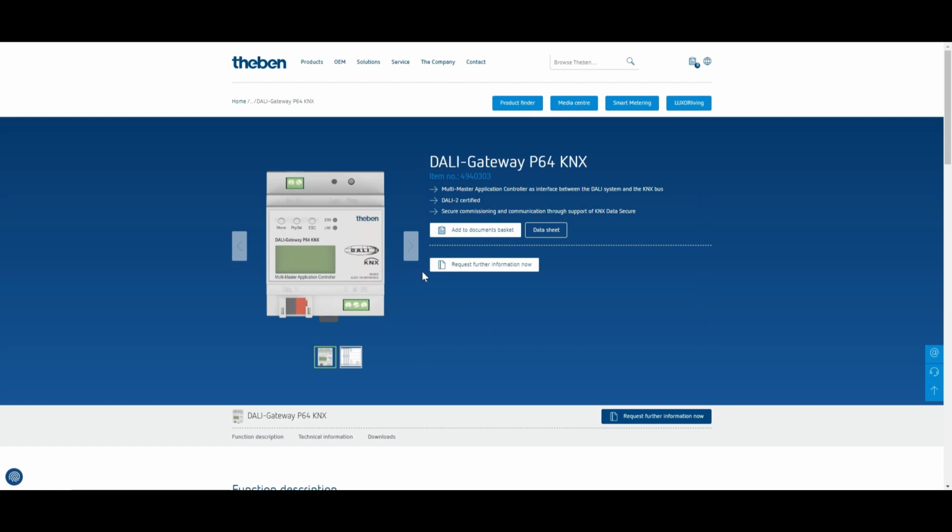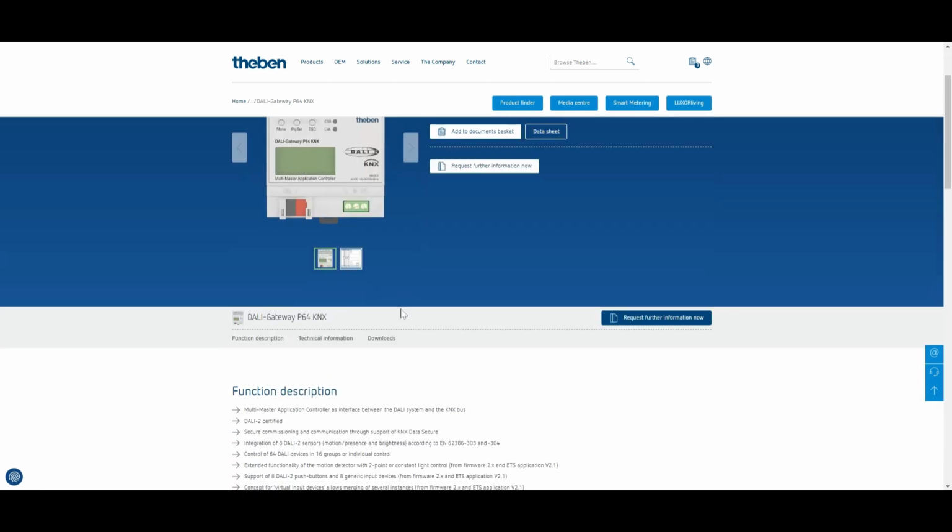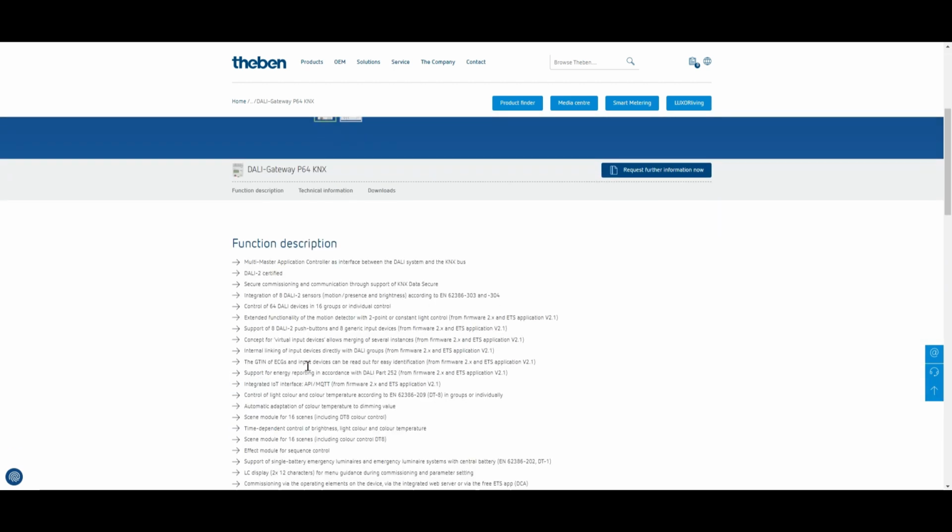It's a one channel. Another interesting point about this gateway is it has an Ethernet connection, so it has the options to be programmed through the DCS app and through a web browser, and that's really interesting for electricians and facility managers and stuff like that. We're going to have a look at that later, but basically it does exit emergency reporting. Another really interesting part of this product, which I've only just discovered, is it has the ability for API or MQTT. Now, that could be interesting for you guys that are looking at exit emergency testing, making your own MQTT server, which we can have a look at a bit later.